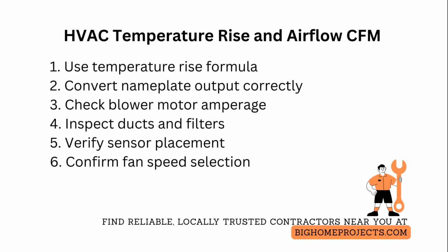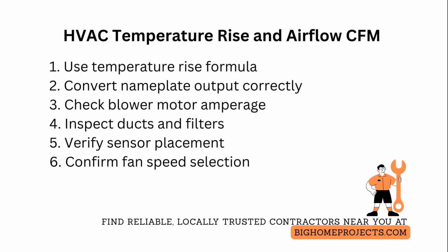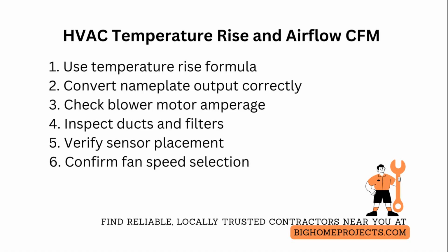For equipment level issues, confirm heat exchanger integrity and combustion safety first to rule out overheating caused by blocked heat transfer rather than airflow. A sealed heat exchanger with restricted airflow will show high DeltaT but different safety code implications. Use a simple balancing move.